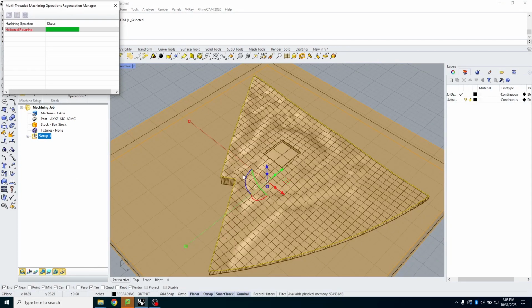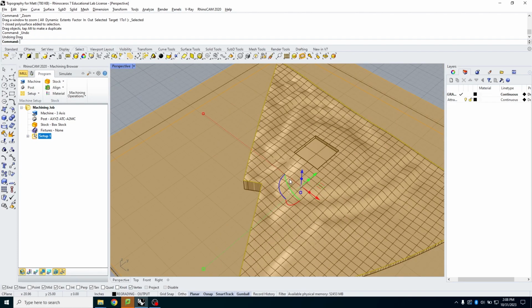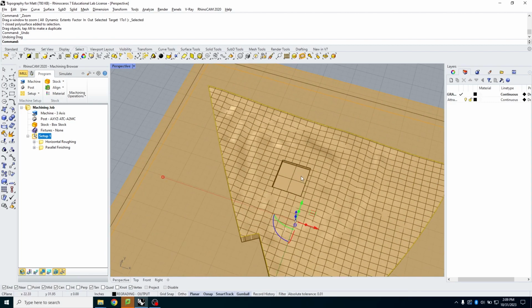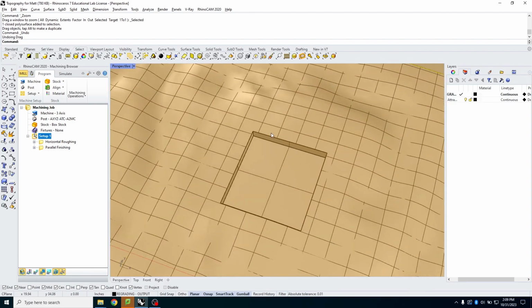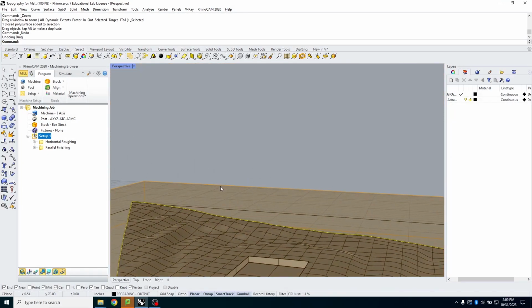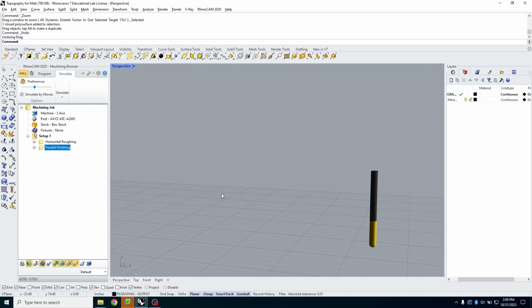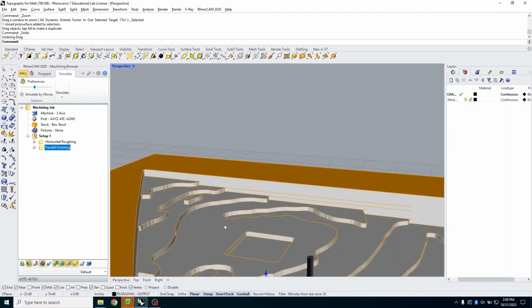And then the last thing on the model to actually set up for is going to be this pocket here for the building. And I'm using that word pocket deliberately because pocketing is a RhinoCAM function. So now at this point, if I simulate this whole job to the end, you're going to see that we're pretty close to the surface.